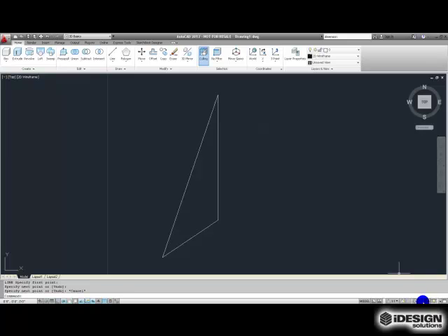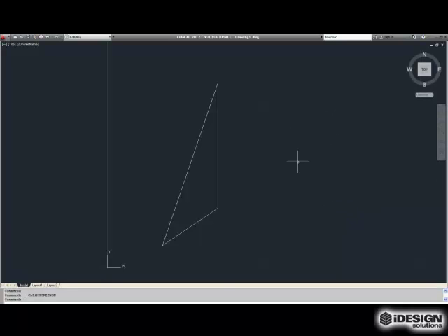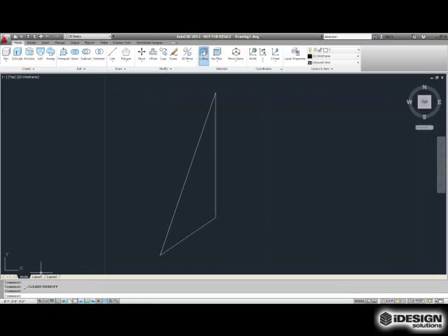You can also turn hardware acceleration on or off, which is a handy feature if you're doing 3D modeling and your geometry is getting quite intensive and slowing your machine down. You can also isolate objects with this light bulb button, and that's helpful if you're in a small area using lots of objects and trying to manipulate them. You also have the option of switching to a clean screen, which gives you more real estate so you can see more of your model or your drawing.